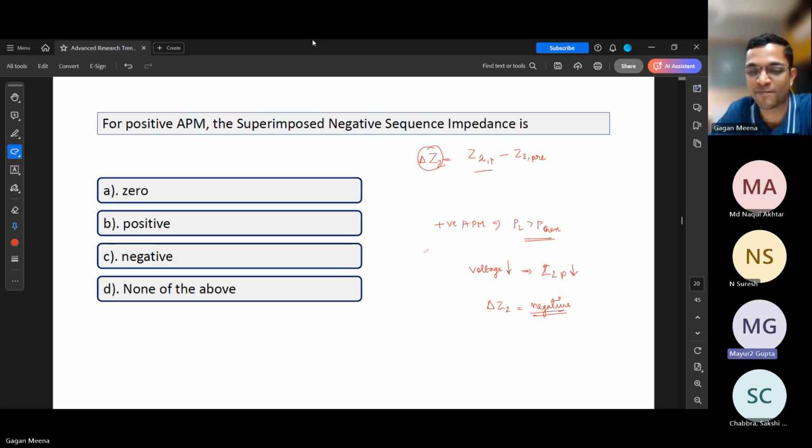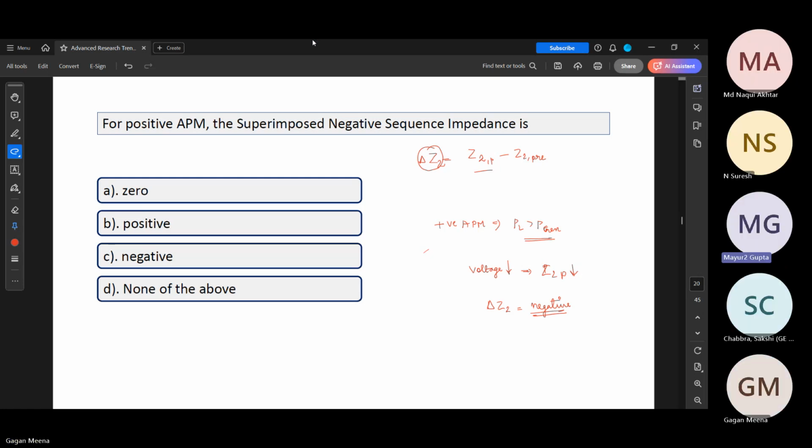Yeah, if you consider an ideal situation, for inverters we consider it like this: if there is a drop in the frequency, then the inverter should operate in a P control mode. And if there is a drop in the voltage, the inverter is supposed to operate in a Q control mode.